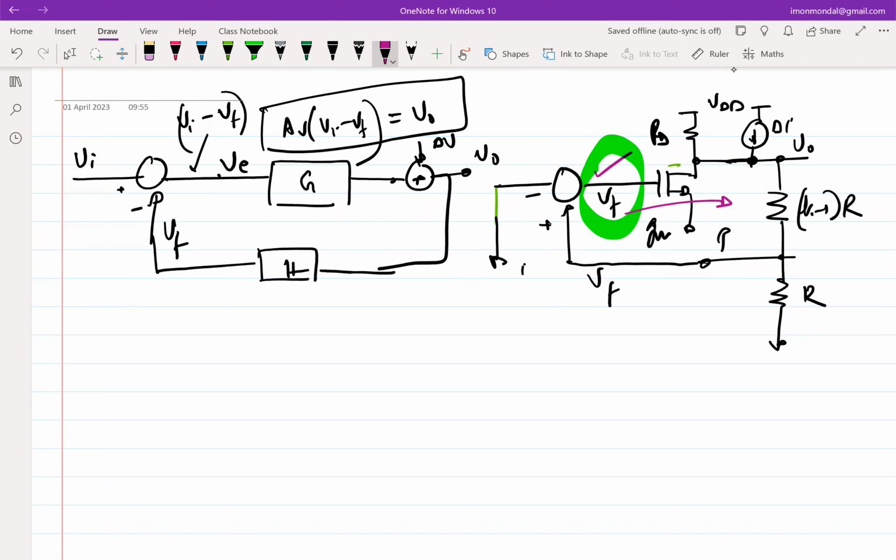So taking this example that we have been doing right now, if you had to analyze this in the forward direction, you probably would have needed the exact gain of the amplifier, right? But the negative feedback loop is constructed with the assumption that the exact gain of the amplifier is not relevant, as long as it is large enough. The only thing that is relevant is the feedback factor. If the negative feedback loop works properly, the feedback factor is what sets your output, right?